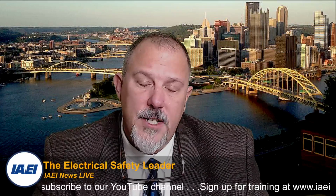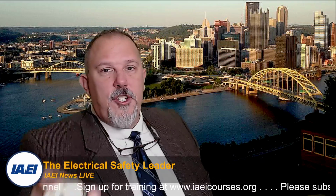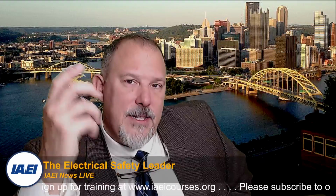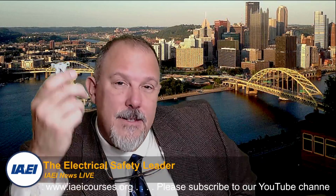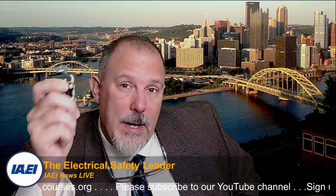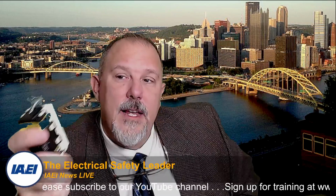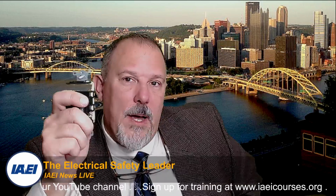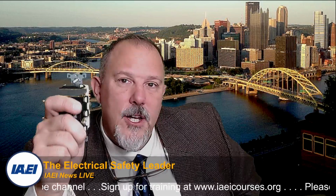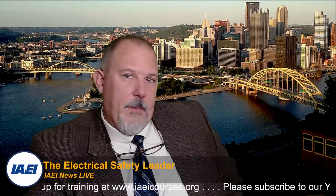Another common question is, how do I test these devices? I'll get a question of, I used my indicator. I used a GFCI handheld test device and it didn't trip my GFCI or AFCI. The way to test any of these devices is to press the test button and press the reset button. That's the way to test these devices. Don't rely on any third-party piece of equipment.